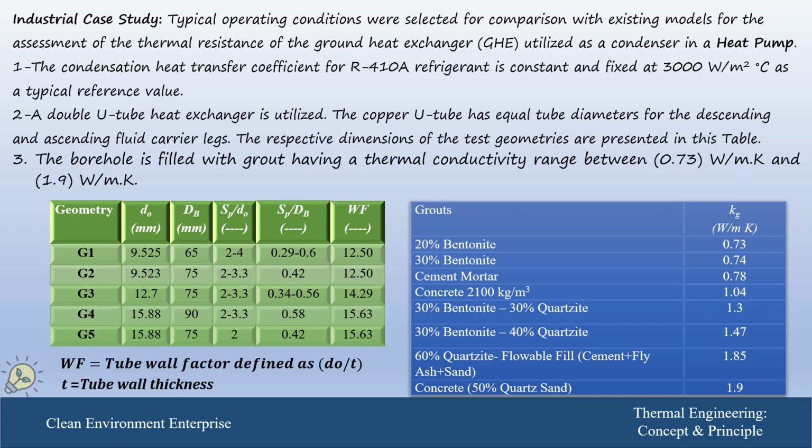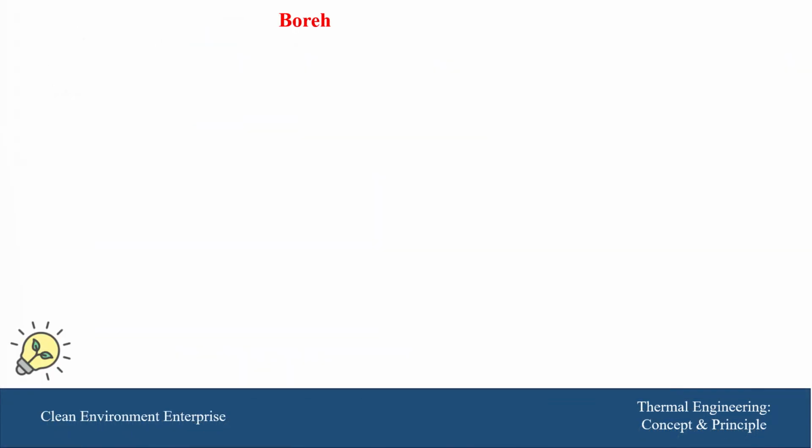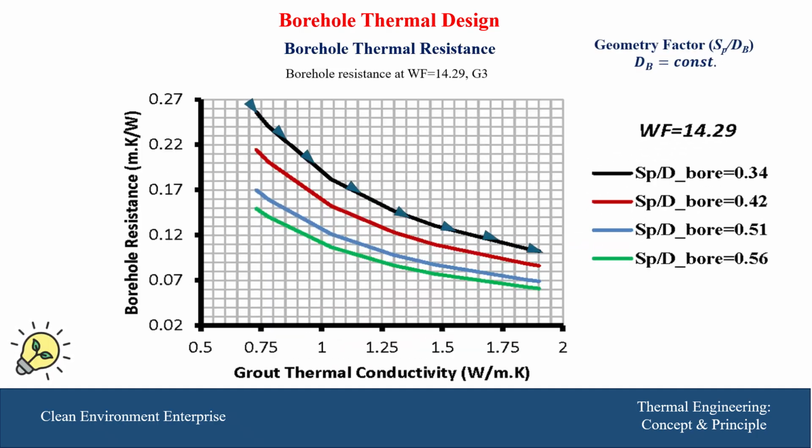So a range of these materials can be used just to improve the thermal conductivity of the grout material, which is reflected on the performance of the tube itself. To compare the borehole thermal design, we will focus on the thermal resistance of the tube.